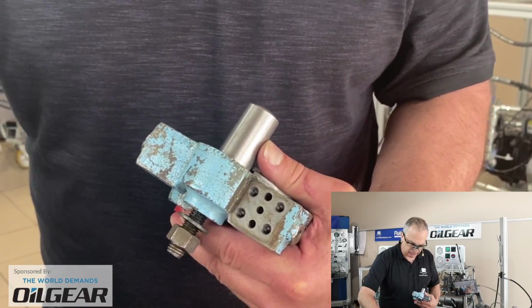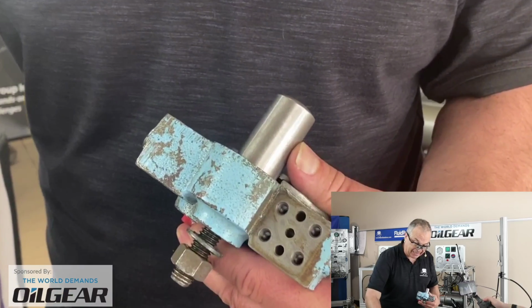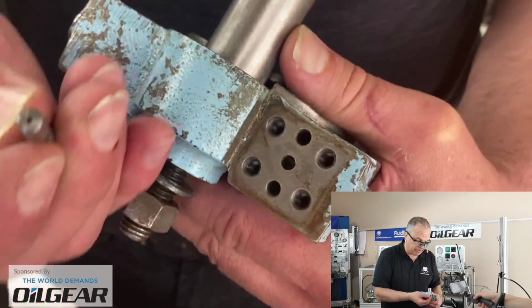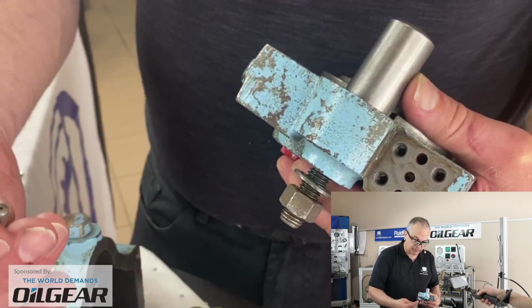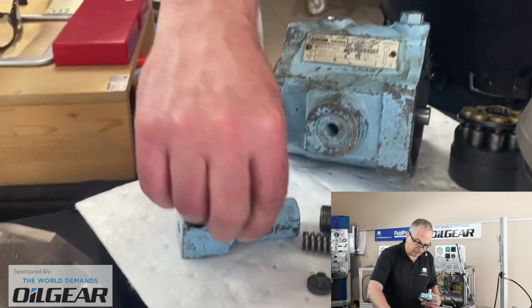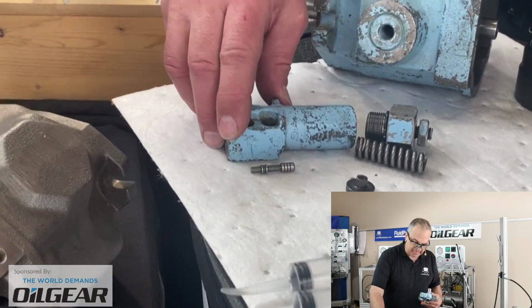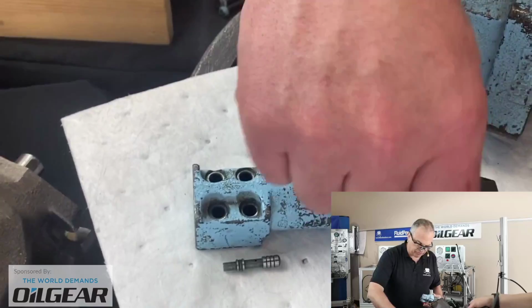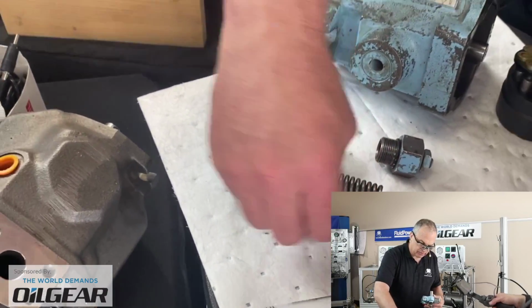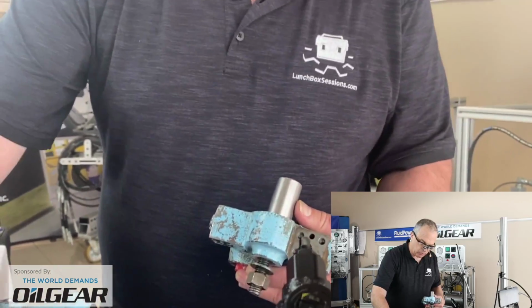Here's our compensator. Make sure that if you ever take a compensator apart, that spool goes back in the right way. Sometimes the bleed orifice in the middle of the spool is meant to be pointed out towards the adjustment, sometimes the other way around. It depends on what internal passages have been set up in there to bleed down the backside of the compensator. So there's the spring, and the cup washer that the bull-nosed end of our spool rides against.